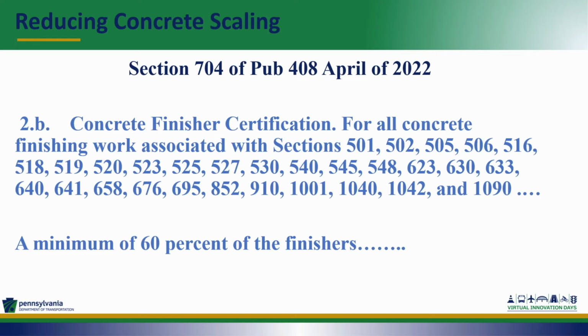So how many finishers need to be certified according to this? It is a minimum of 60% of the finishers, and we had a lot of discussion about this number at our Construction and Materials TAG. Why 60%? Well, it's going to require that most of the finishers be certified. It should address any kind of staffing issues, especially if you have newer people coming into the industry, to give some time to get certified. But the key is that we'll have the majority of our finishers out there certified. So if you have a crew of 5 folks finishing your concrete, 3 of them need to be certified.